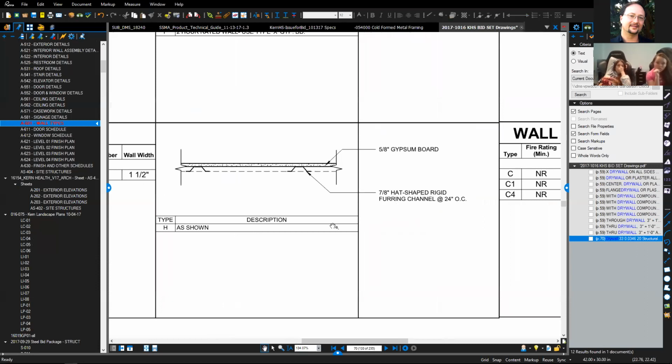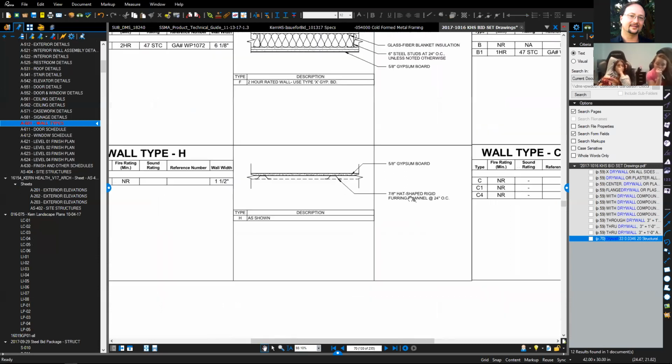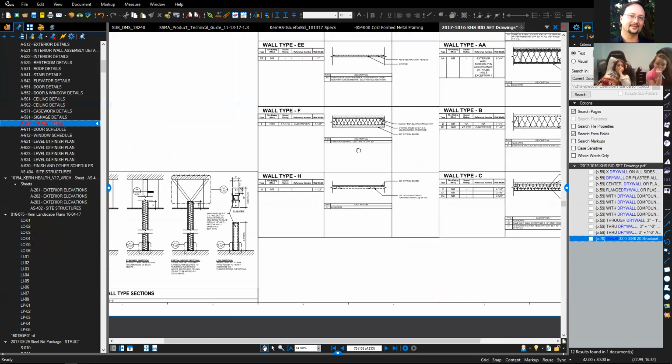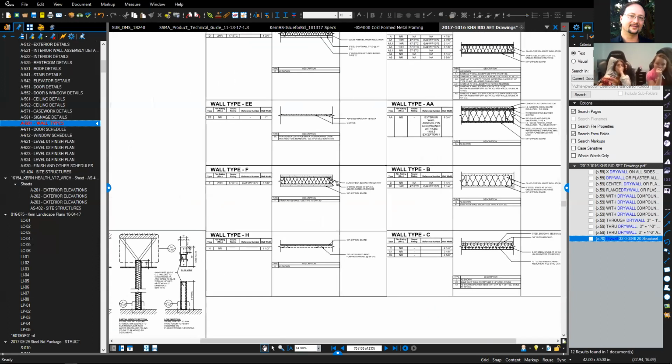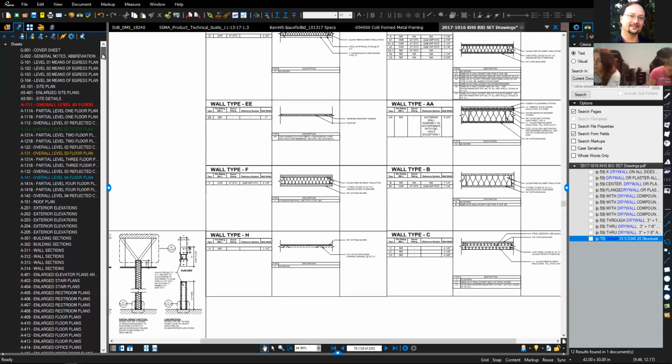I would say yes. Yes, if we have the drywall scope, this affects us. Okay, so we may not have seen it on that page, but that's what I go through. As I go through the wall types, I go through the plans, the floor plans, wall types, and then if we have a ceiling scope, I'll go through the reflected ceiling plans, which is here.